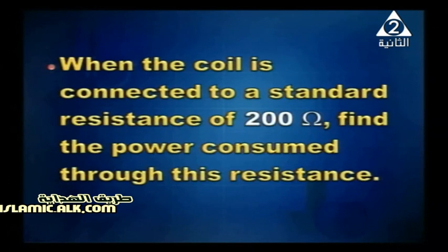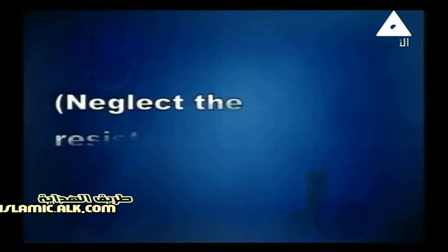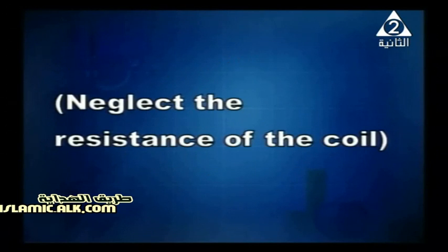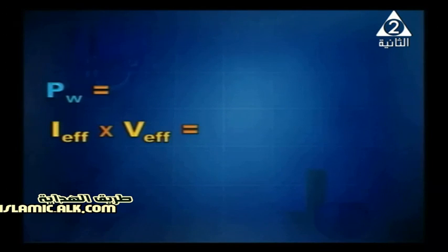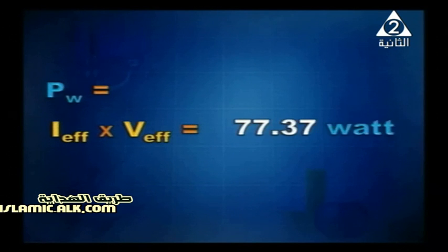Another item of the same problem, if the coil is connected to a standard resistance of 200 ohm, find the power consumed in this resistance. Neglect the resistance of the coil. Power is given from the formula I effective times V effective. Okay, so it will be 77.37 watt.